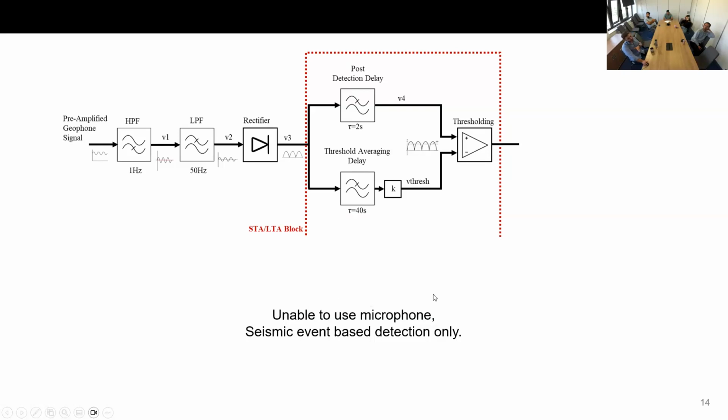I mean, it's expensive and requires other amplification stages and a lot of stuff. So that's why we switched to the geophone only. After the amplifying stage, which is an op-amp circuit with more than one amplifying stage, we have an overall gain of more than 60 dB.